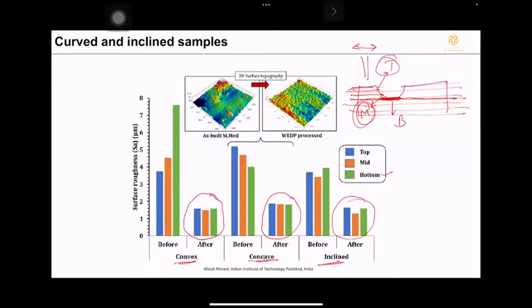Now, because of that laser scan, the bottom layer is still hot, and this is exposed to the gas outside, because here there is no more printing needed. So what happens to this surface if we melt layers on top of it? So definitely these powder particles will get stuck on this surface, because this is the bottom part, and the recoater blade has just covered the whole surface with fresh powder. So this spatter may get stuck to this surface, and this is the reason.